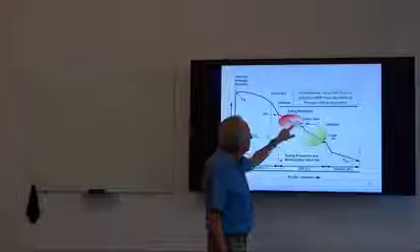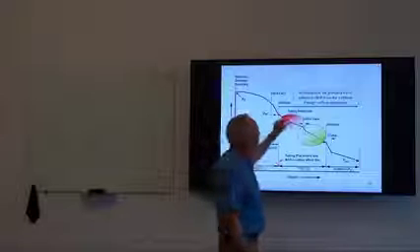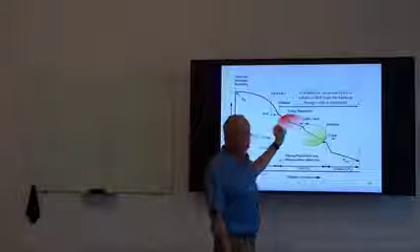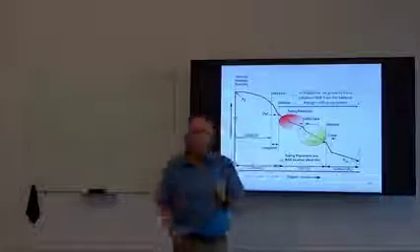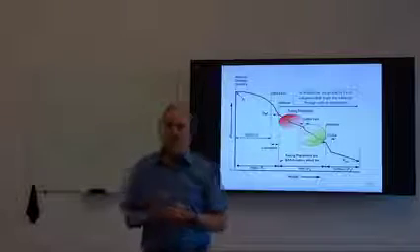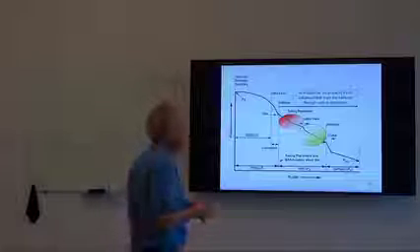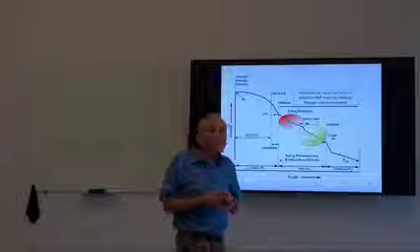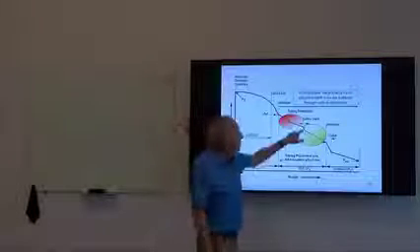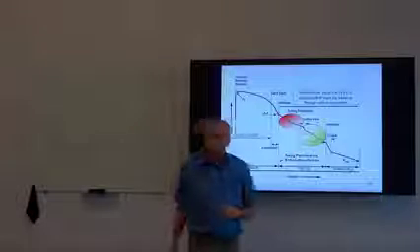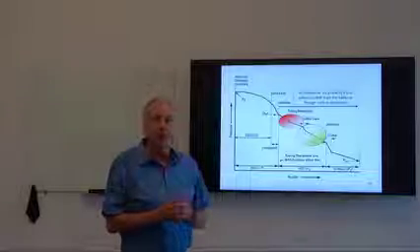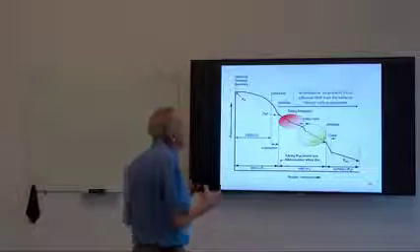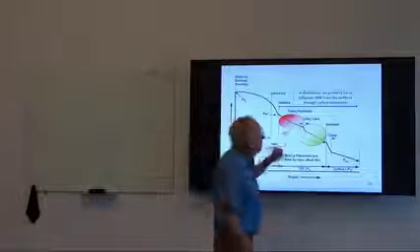There may be some things in there, for example, tubing restrictions that cause a sharp drop, it might be small, but a sharp drop due to some restriction, perhaps some scale, or we may have paraffin buildup in the well. We may have something like a safety valve or an intermediate nipple, something that gets in the way that gives us another pressure drop.